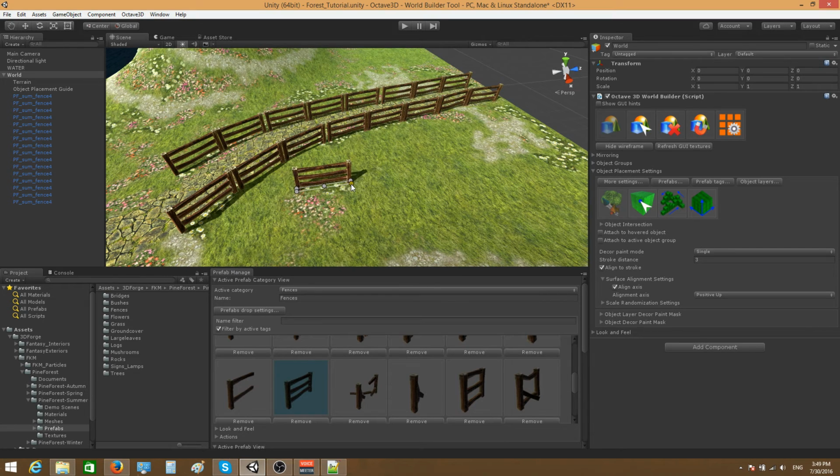And secondly, the pivot points. When you're using this align to stroke functionality, I highly recommend that you use one of the corner pivot points that is closest to the initial direction in which you want to move the guide. I would avoid using the center pivot point for objects like fences, objects that are basically thin, because it doesn't really give good results. The center pivot point might be useful when you're working with cube objects or something like that. So just keep this in mind when you're working with the align to stroke functionality.